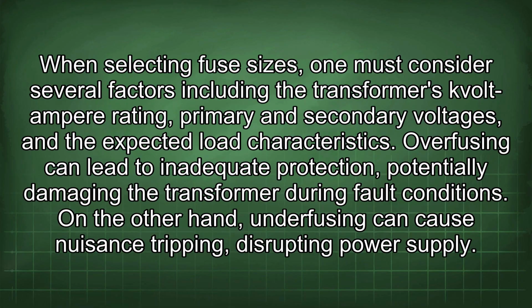When selecting fuse sizes, one must consider several factors including the transformer's kVA rating, primary and secondary voltages, and the expected load characteristics. Overfusing can lead to inadequate protection, potentially damaging the transformer during fault conditions. On the other hand, underfusing can cause nuisance tripping, disrupting power supply.